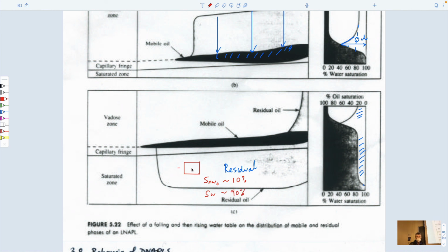And so if you wanted to calculate the rates at which dissolved components would be carried downstream, we can do that, because we know how to calculate fluxes as a function of relative permeabilities, viscosities, and pressure gradients, which is Darcy velocity. And if we know Darcy velocity, we also know that advective velocity is equal to Darcy velocity over porosity.